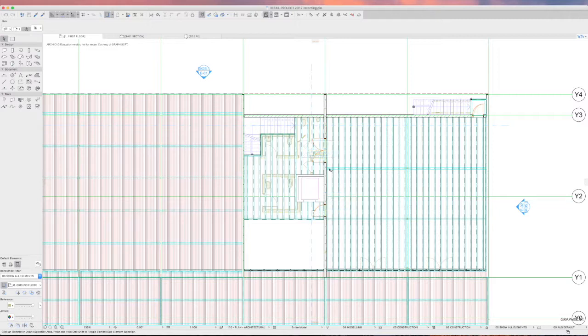So I decided I could delete one beam because we've got enough concrete block walls that could be used for support. But we need to keep this beam here because I want the floor line to extend out past the front of the elevator opening. So you can see I've added some new posi strut floor joists.